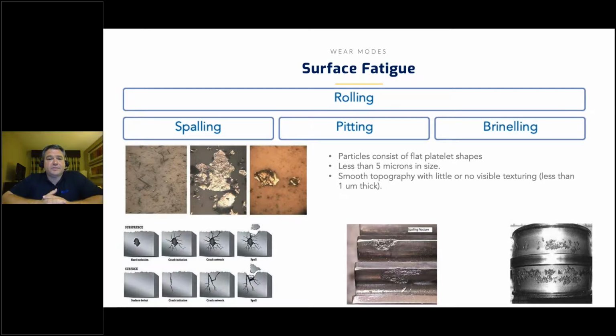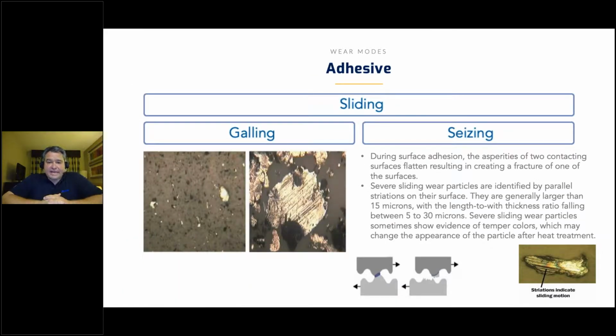So that's surface fatigue. And then there's adhesion. That's when the lubricant's just not doing its job. One of the cool things about a lubricant, oil has this great property that when you increase the load and pressure on oil, the viscosity goes up. It becomes thicker. It even becomes like a solid. So it keeps that barrier between those two parts as your gears are rotating and meshing together, meshing in and out and sliding. That oil's doing its part to try to keep those separated.